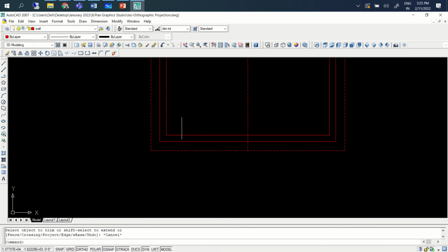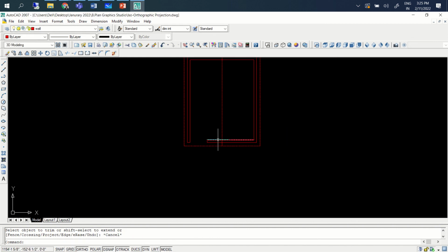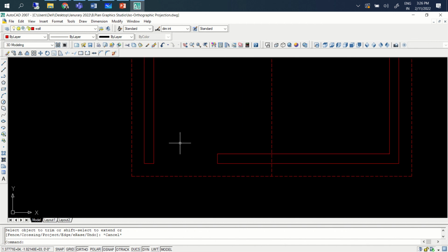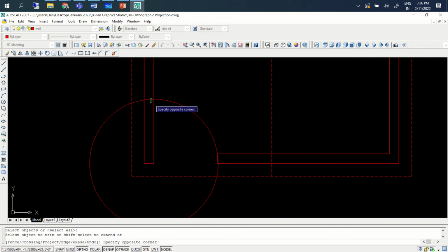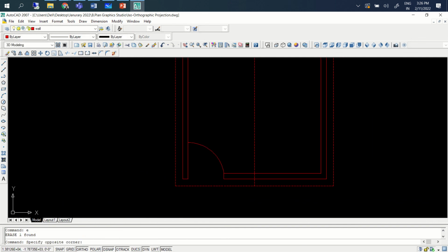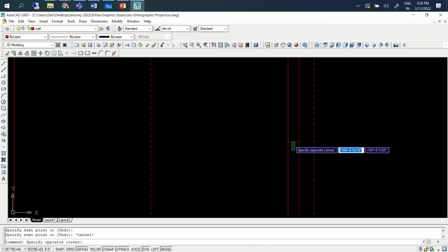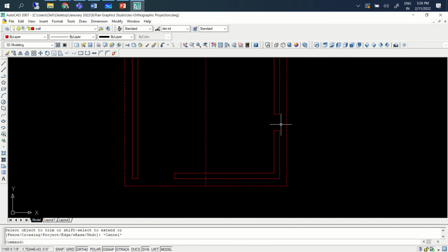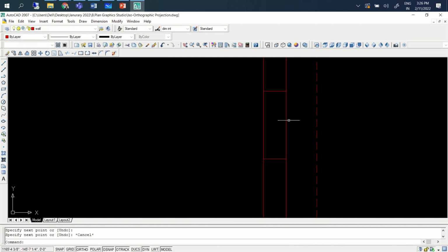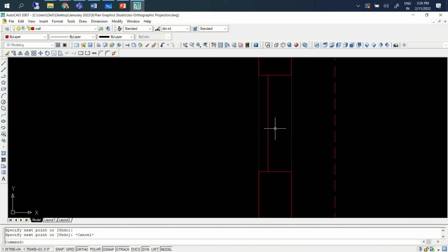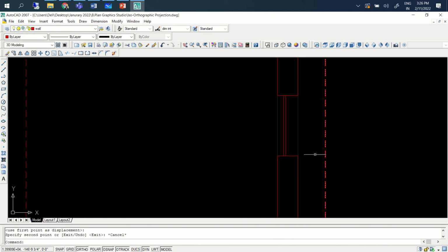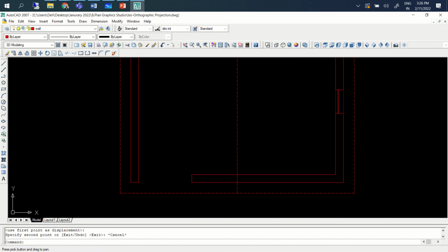Let's add a little bit more. This is the entry, the opening to the shed. I'm not showing how to draw doors at the moment. I'll just leave it like that, because I think you will learn these things a little later. This is a door entry, and let's put one small opening here. Like I said, this line should not be the same as that of the wall. I'm just keeping it in the hidden line. I said just draw two lines. So we have a door and we have a window.